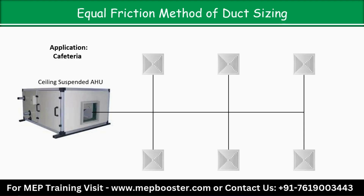Once you get the cooling load value, based on that cooling load and supply air CFM, you have to do the diffuser selection. Let's say we have selected 6 diffusers, and the total supply air CFM from the cooling load calculation is 1200 CFM. How much air do we need to supply from the ceiling suspended AHU? We are supplying 1200 cubic feet per minute.